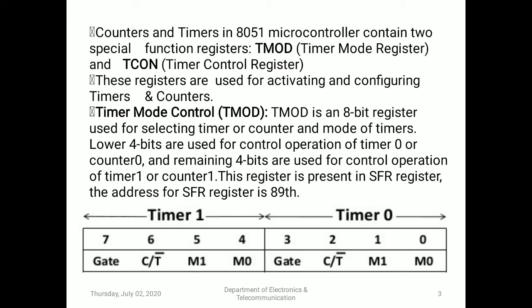Okay, so if we are talking about the timer here, either timer or counter uses two SFRs from the 8051 SFR section. SFR means special function register, and the first one is TMOD, the timer mode register. In that, which timer is selected is identified. After selection of timer 0 or timer 1, we have to select the timer operating mode. Here in the diagram of TMOD it is mentioned as M0 and M1, or in some cases it is mentioned as,